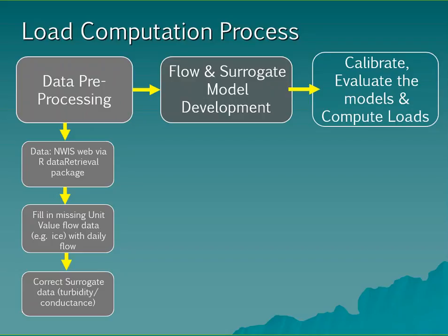Very often as you're going through using surrogates, like a YSI, you'll get spikes or just random things that sort of creep into it. So we had to clean that information up. Now when we did this, we also developed a little bit of a different kind of system here. What we did is we interpolated all the data that were missing if there was a gap less than 2 hours for the surrogates. But if it was more than 2 hours, we did not fill that data in.